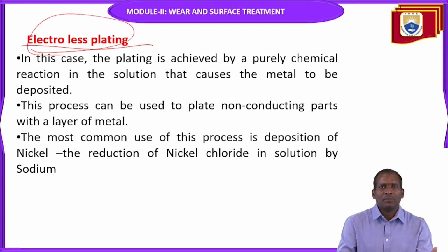This process can be used to plate non-conducting parts with a layer of metal. The most common use of this process is deposition of nickel, by the reduction of nickel chloride in a solution by sodium hypophosphite.